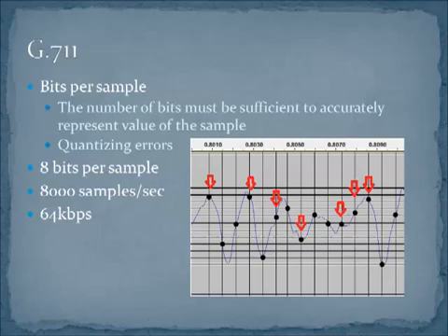So here is a grid that I'm going to overlay on top of this audio signal. And the red arrows indicate some of the sample values. So all the vertical lines are where I'm going to take sample values. And these red arrows happen to point out problem areas. So the vertical lines are where we're going to take our samples, and we do this a whole bunch of times a second. The horizontal lines are the actual values that we assign to the samples.